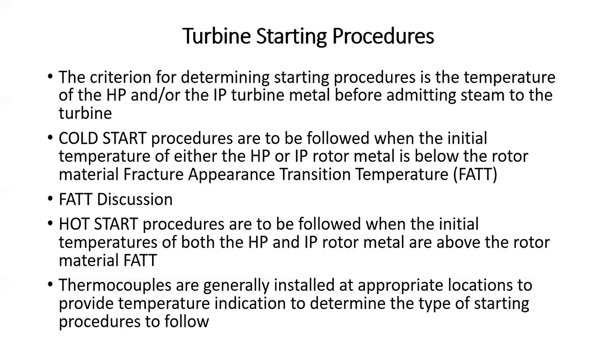Basically what they do is they drill through the casing to the point they're almost just about 1/4 of an inch away from bursting through that inner casing. It's a pretty small hole, just enough to feed a thermocouple down, and then they'll put some sort of thermal fluid in there to transfer heat effectively, and then immerse the thermocouple in it and push it all the way down. So that thermocouple is really on the stationary side, opposite the location on the rotor that you're interested in